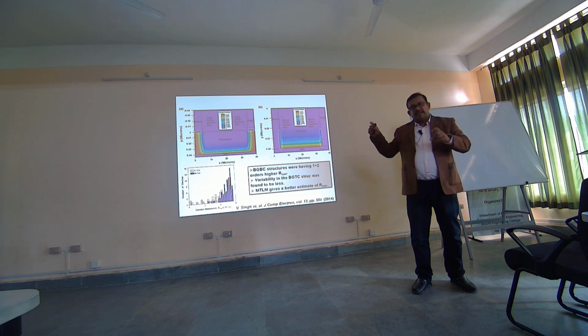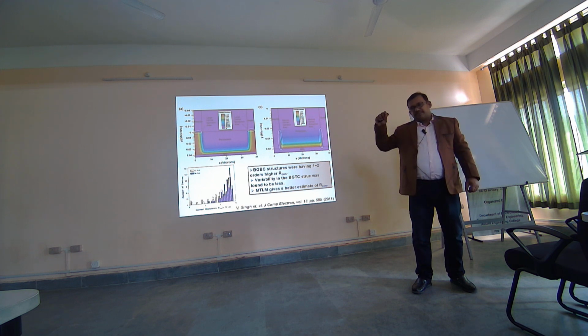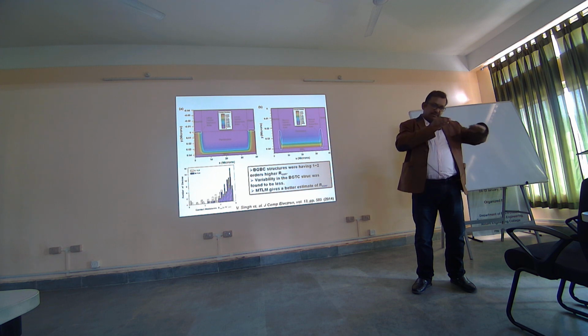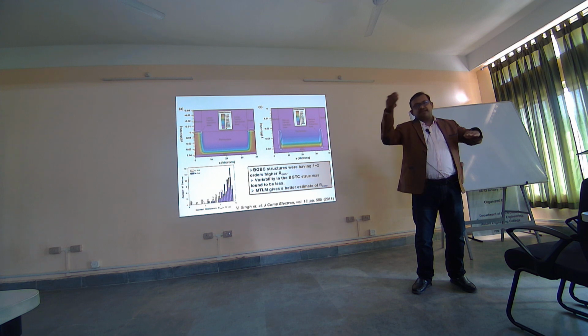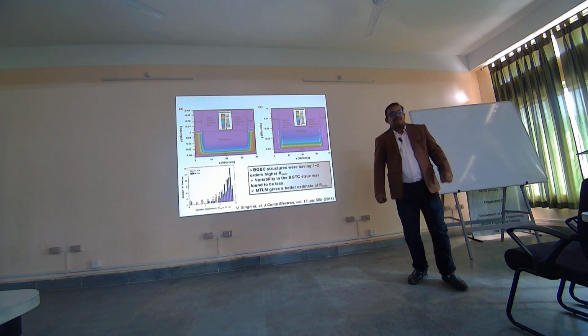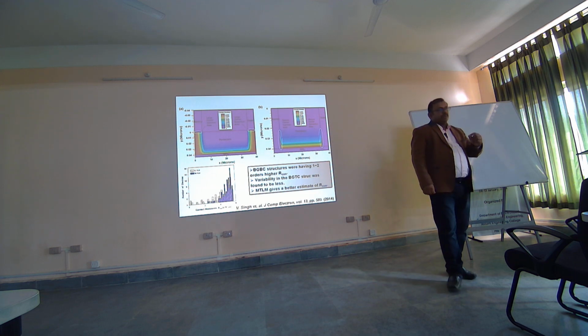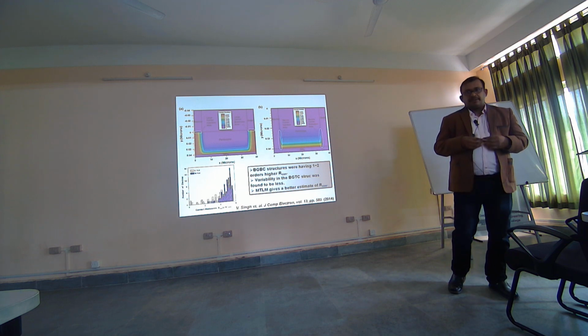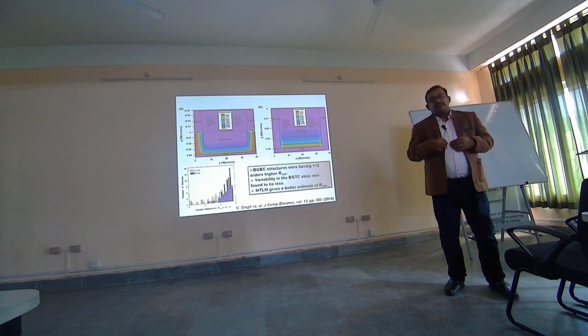That is where the analysis of the surface by the contact angle method is very critical, because it helps in understanding what the surface energy of the substrate is and what the surface energy of the next layer that I am going to deposit is. If they are well matched, then those kinds of things will not come. And then, of course, you have to be careful that you may be annealing at a higher temperature than required, so you can change that as well.